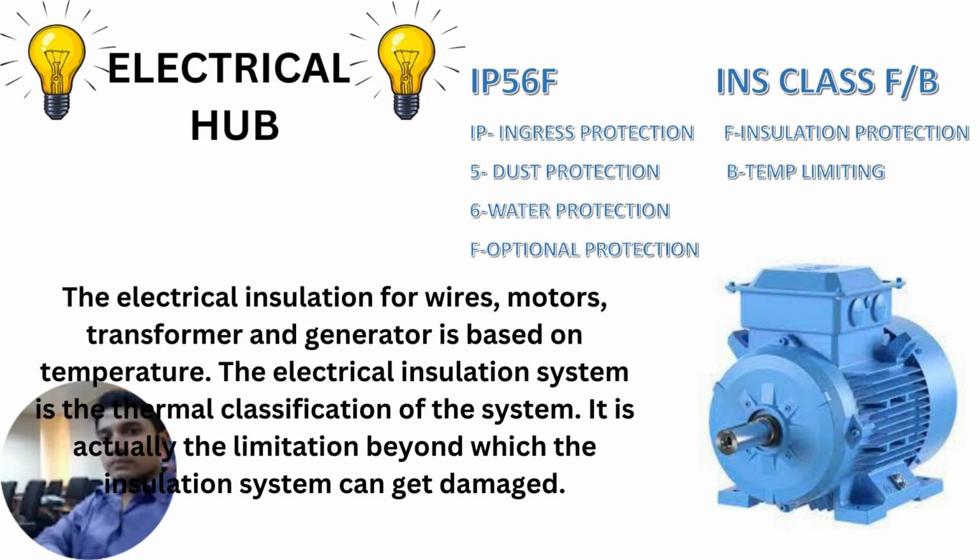Now let us start our discussion with the insulation class of the motor. The insulation class is the thermal classification of the system. It means that beyond that temperature, the quality of the insulation will start degrading.